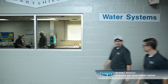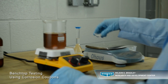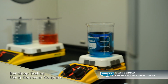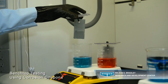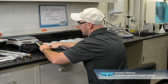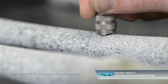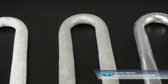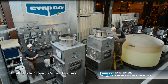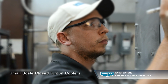In support of customer requests for better commissioning outcomes, Evapco initiated a study of commonly conducted laboratory test procedures historically used to investigate the formation and control of white rust. Preliminary research results indicated that commonly used benchtop tests, including corrosion coupons, did not correlate well with data from operating evaporative cooling systems. With this insight, Evapco built industry-leading research equipment at their Wilson E. Bradley Global Research and Development Center, specifically designed to evaluate white rust formation on evaporative heat transfer surfaces. Evapco designed and produced 2 small-scale closed-circuit coolers to replicate the dynamics experienced by customers' evaporative cooling equipment that is commissioned with immediate heat load.